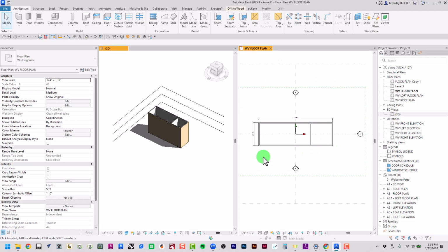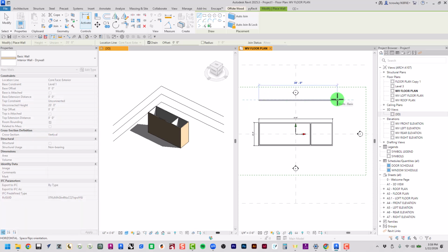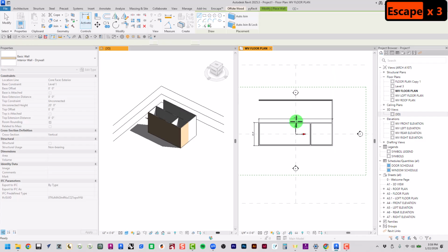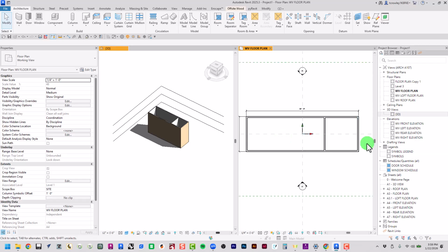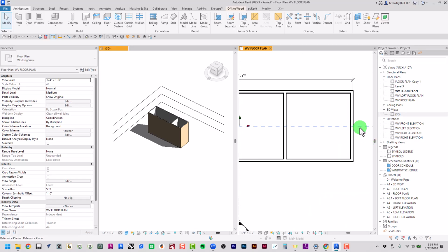So our wall seems to be 10 feet away from the right side. So if I go to annotate, align, I'm going to select this wall here, and I'll select this wall here. When I'm using the dimension tool, I can choose where I'm dimensioning from, and I can dimension from the wall center lines, wall faces, the center of core or face of core, and typically I'm measuring from the face of core. When we're creating these documents, typically we're measuring to structure.